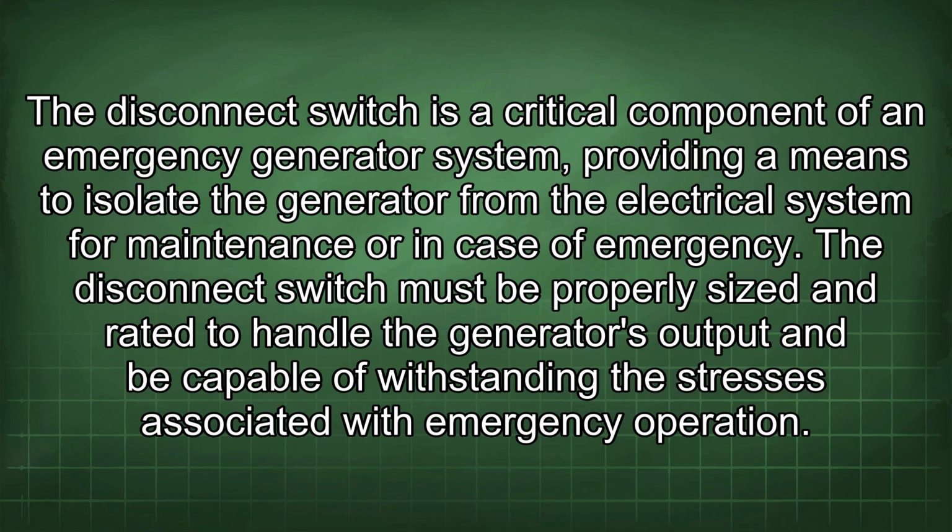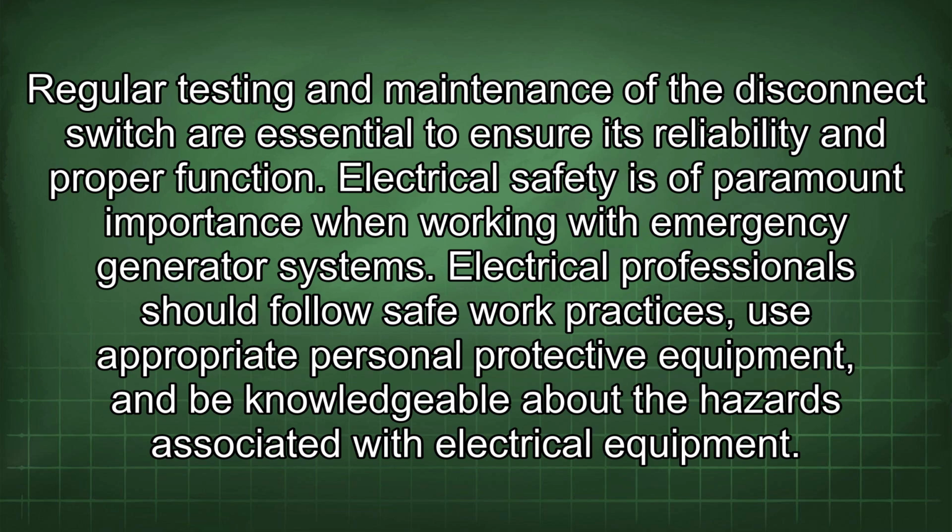The disconnect switch must be properly sized and rated to handle the generator's output and be capable of withstanding the stresses associated with emergency operation. Regular testing and maintenance of the disconnect switch are essential to ensure its reliability and proper function.